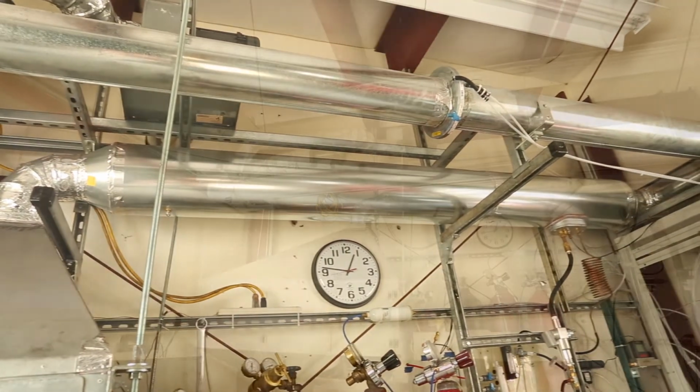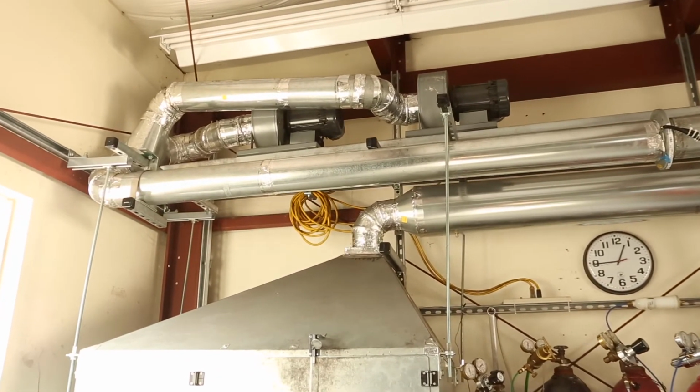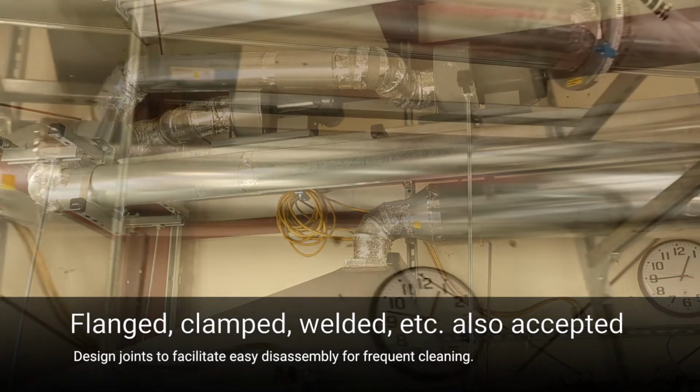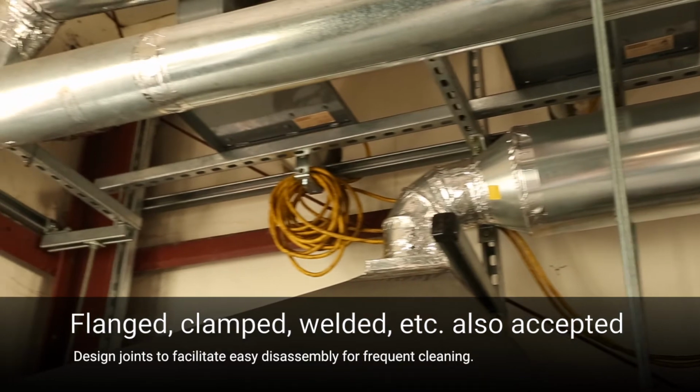Ducting sections are joined together to connect the testing hood to an inline, squirrel cage type blower. The ducting sections are sealed together using an aluminum-backed tape. This tape should be regularly inspected to ensure that there are no potential leaks at the seams.